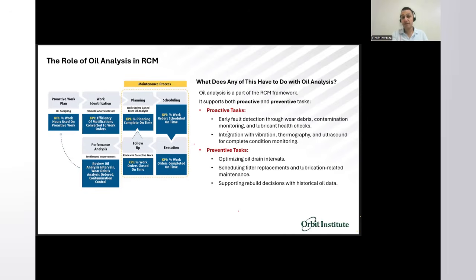Oil analysis can be a preventive task as well. If you are only using oil analysis to optimize the oil drain interval, to schedule the filter replacement for the oil, for example, or to support rebuilding decisions with some historical oil data, all of this is a preventive approach of oil analysis that can still fit in your reliability centered maintenance program.